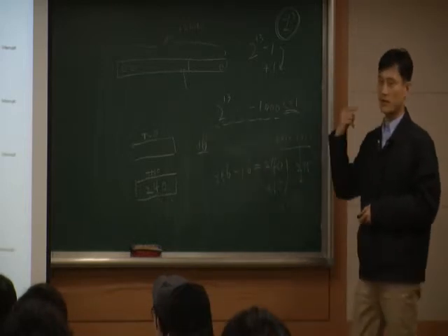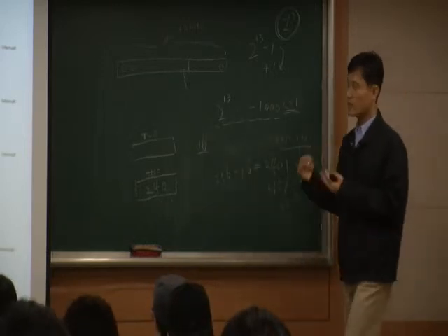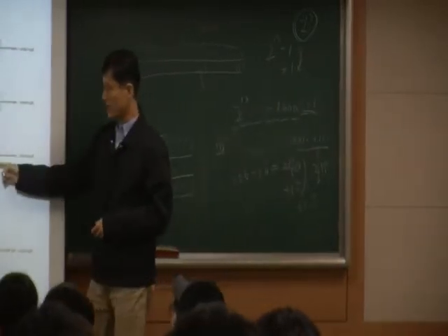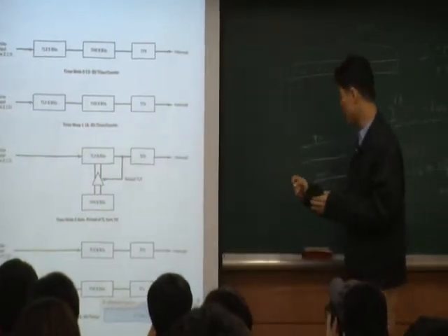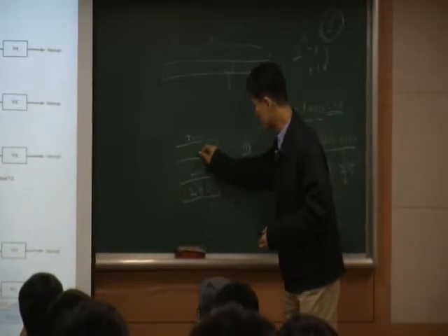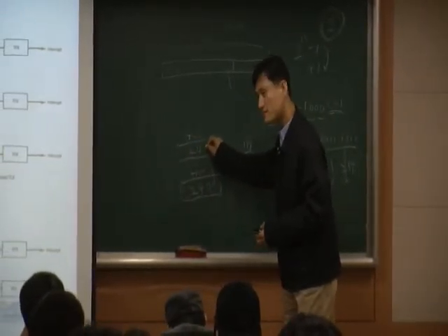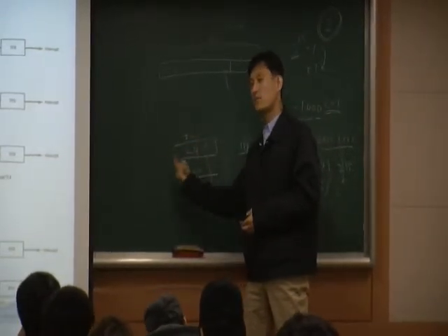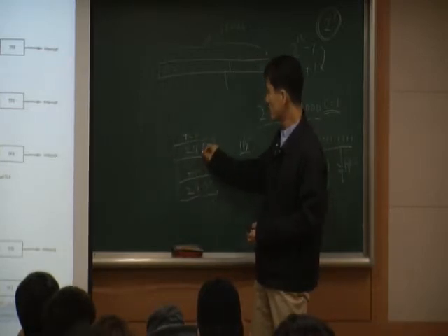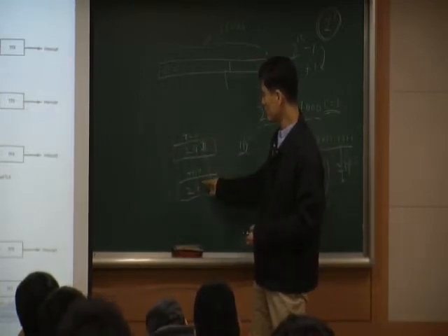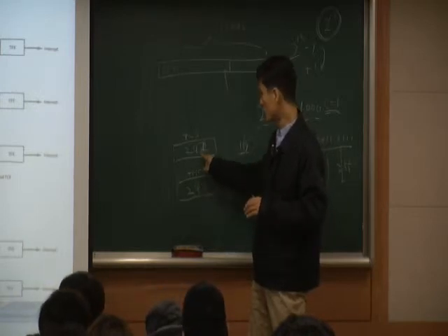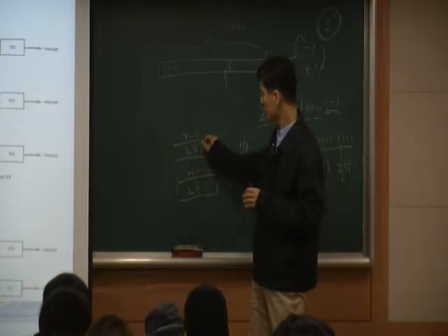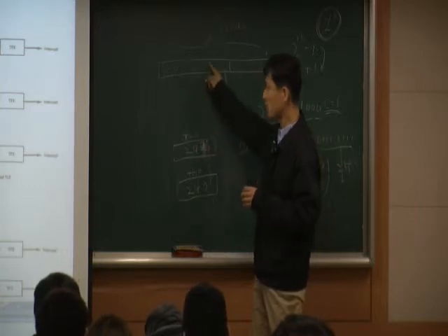And then run the timer. Then the hardware, as you see here, will automatically get this value and write it here. So hardware will copy this value here. And then every time you get a pulse, you increment: 241, 242. This one is the same, right? You don't change anything here. But this one is basically a counter, so it keeps incrementing like this, same way.